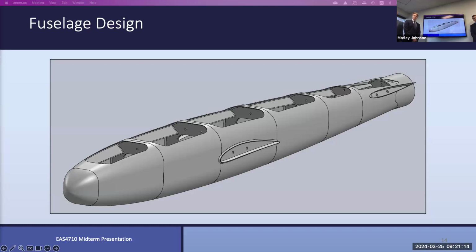Why do you need to assemble the landing gear before you put all the fuselage sections together? Why do you need an opening on top? Well, for example, the rear landing gear in this section: the fasteners come from the top down, so you assemble them first, and then you put the fuselage together. But if the access hatch wasn't there, it would be hard to do.